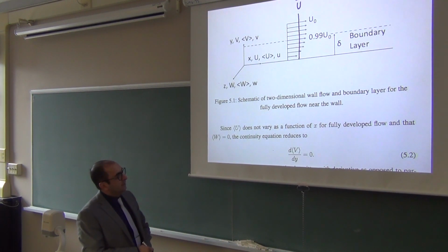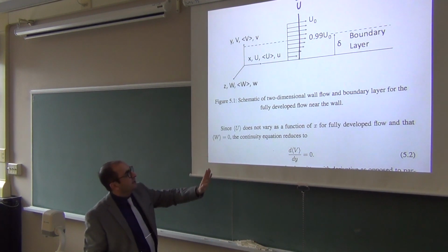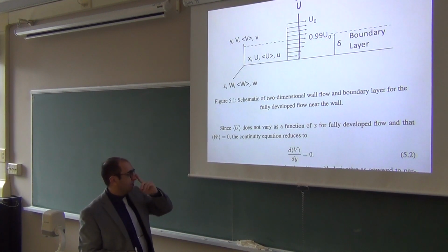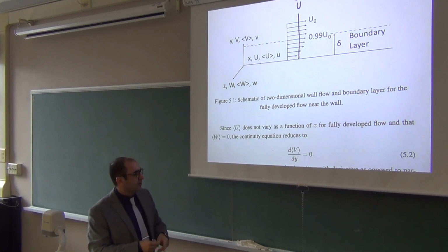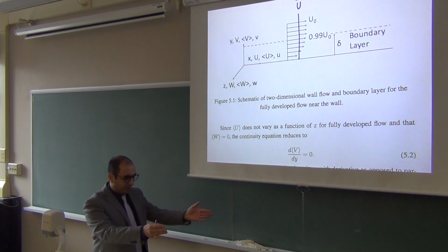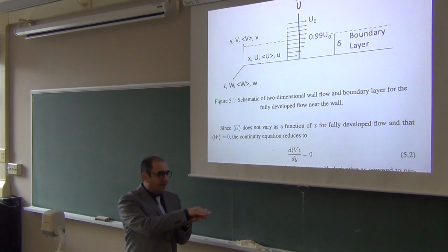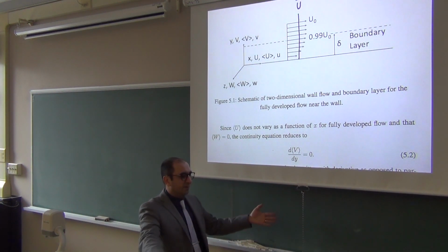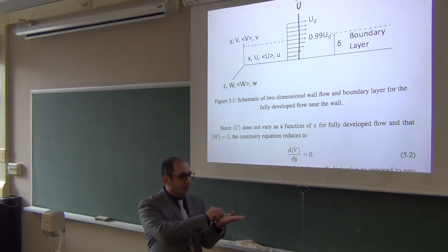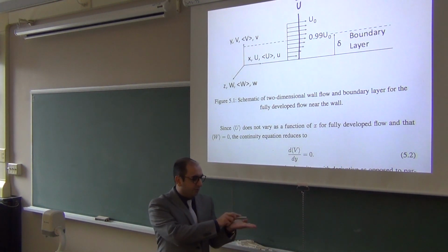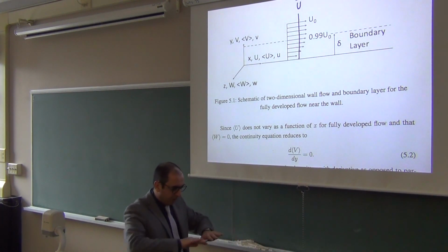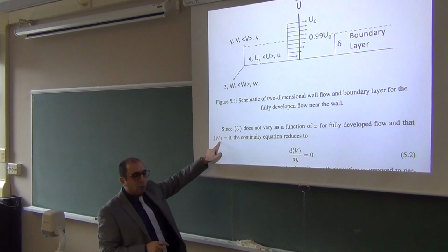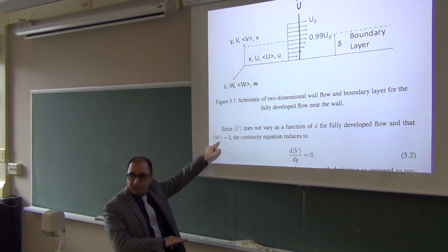And that the mean velocity in the span-wise or sideways direction is 0. Okay, so how do I support this claim? Well, I have a very symmetric sort of flow, and flow is going along the x direction in the boundary layer near the surface. If this is a fully symmetric infinite field, there is no reason why the flow should steer to the right. There's no reason why the flow should steer to the left. For the perfectly symmetric and homogeneous condition, the flow will just go along. It's not going to steer to the left or right. So I just supported this claim. There's no mean motion sideways. It just goes forward.